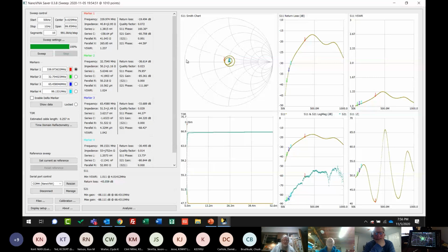I'll be honest. It's at about 25 feet on a good end and about 12 on the other. It's an off-center fed dipole that's shortened with a coil because I've only got about 67 feet that I can get out of it from the corner of the house. But enough excuses there. We know that it's an antenna, and any antenna is better than no antenna. So let's see how it performs.